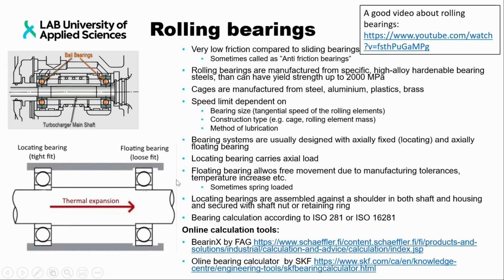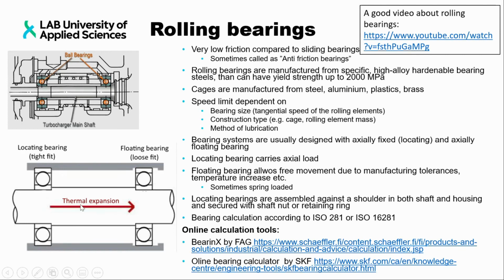Here is a better picture of it. And the reason is that in many applications you have thermal expansion, and therefore you need to allow the thermal expansion to happen in some location, and that is done by allowing one bearing to move freely. And then it means that the bearing which is not moving freely is providing the axial load carrying function.